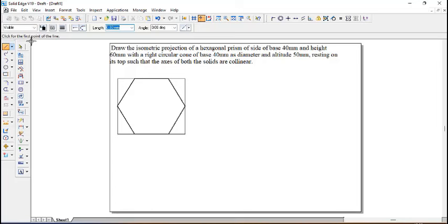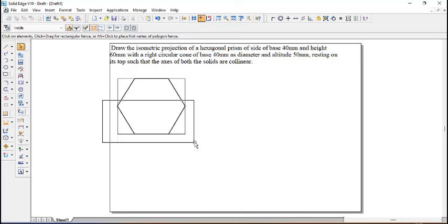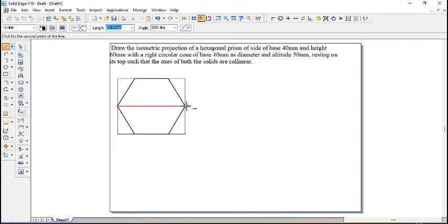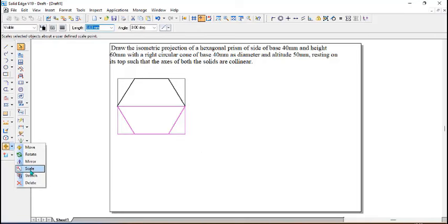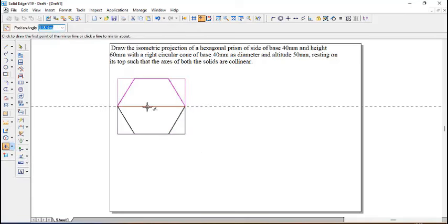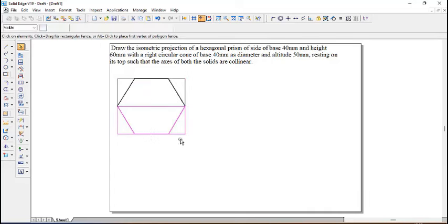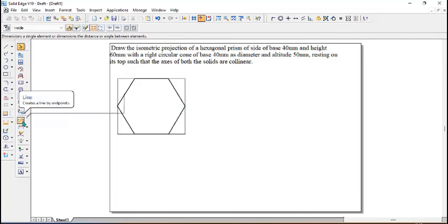We have the projections here, or else, once you do the lower portion of this one, you can drop a diagonal, select the lower portion, and use the mirror command to mirror it up. That is also fine, anything is fine for us. Once this is done, we need to go to the smart dimension. I hope you have understood this.